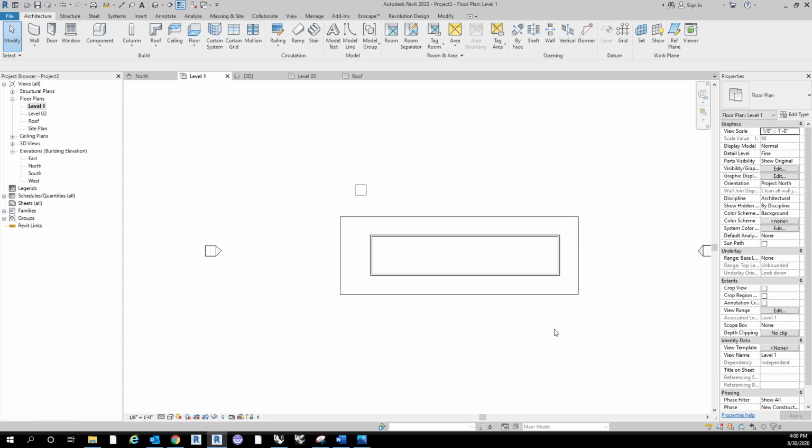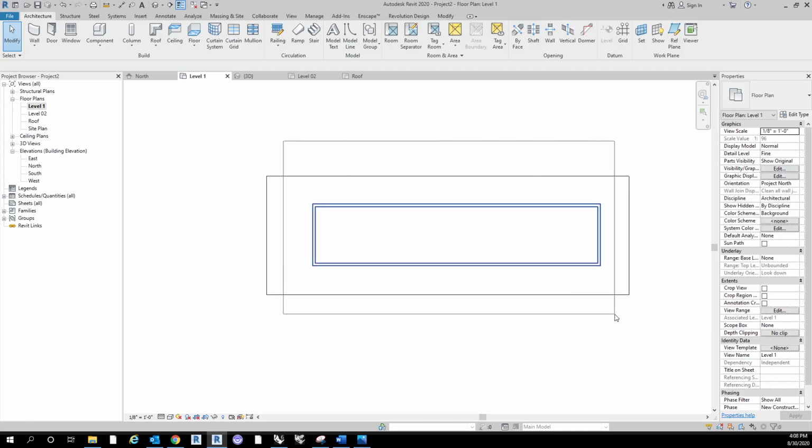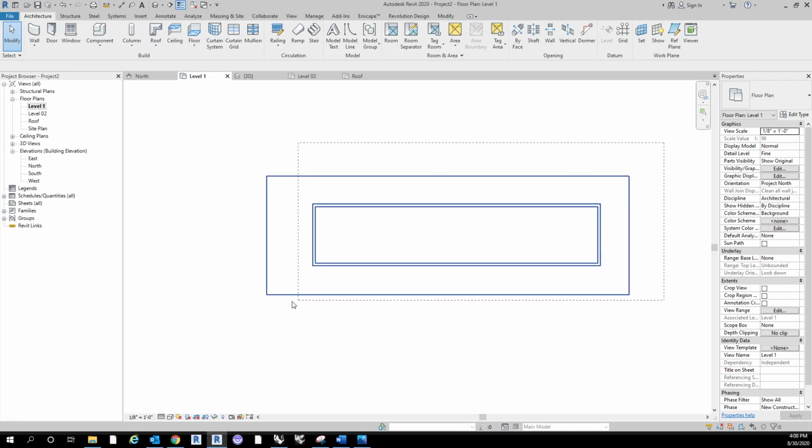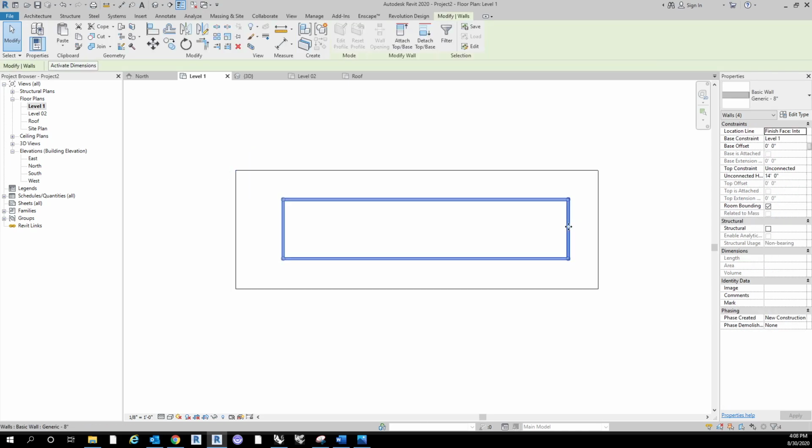All right, and let's kind of center this. So real quick, if you click and drag from left to right, kind of like AutoCAD, it only selects what's in the dialog box that you clicked and dragged. But if you go from right to left, it selects everything that dialog box touches. So I just want those inside boxes. So you can click and drag different geometry. You can also use the arrow keys to go up, down, left, right, whatever you need. So this is relatively centered.